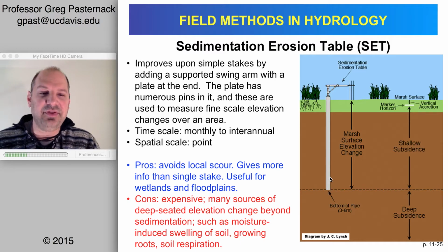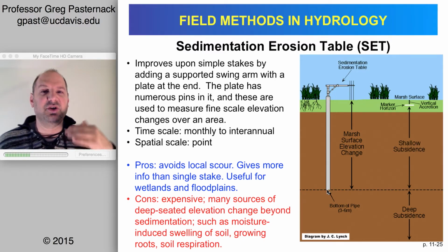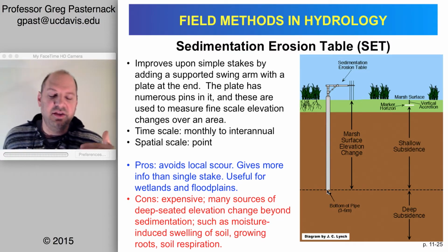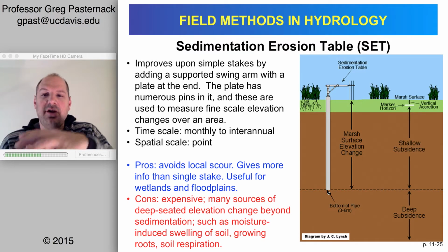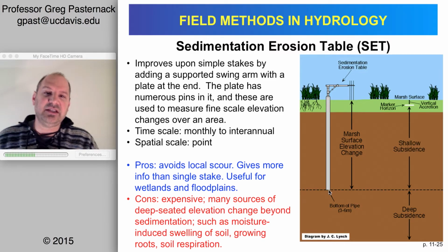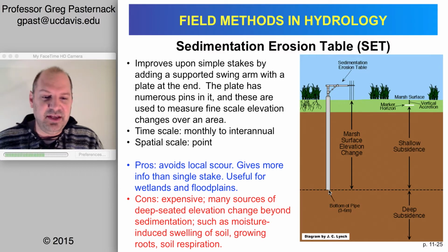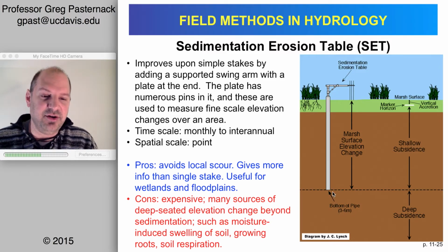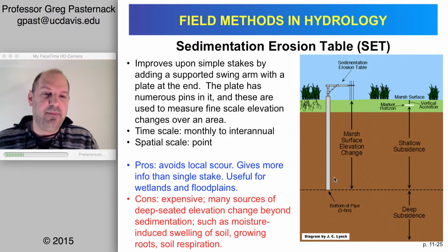So without worrying about that part of it, you put in a pipe, and the bottom of the pipe is the reference elevation that, if the ground under that is swelling or shrinking or something, then the whole thing is going to be moving with that. But by putting that in as far as you can, in this case recommending 3 to 6 meters, then you're establishing a pretty big range over which you're evaluating change compared to your underlying benchmark.